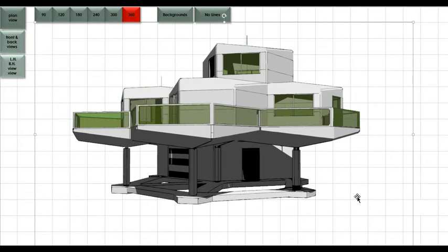Okay, I was saying that the connection between the wall panels downstairs and the columns is what's called a resilient friction connection, by which, in a very severe earthquake, the damage you get is in that connection, basically. It's a friction connection. It's made to be easily repaired, but there will be absolutely no damage upstairs. I'm talking about if you have a suspended casing for your dishes, that will not disconnect from the ceiling. That will stay in place, and we have had these great experiences over 35 years where there was zero damage.